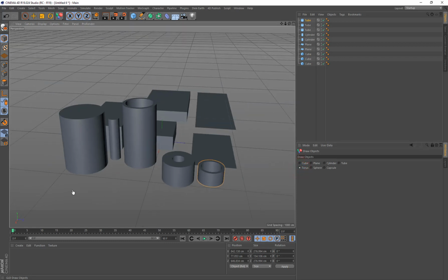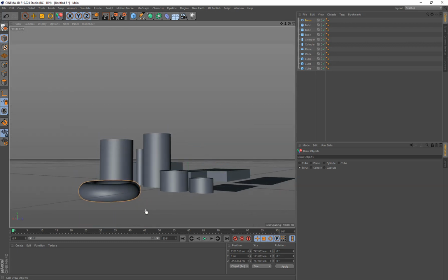Torus, a little bit interesting as well. You drag to define the outer radius, you let go, you may not see anything, because now you're defining the radius of the torus itself. And you're doing that by dragging up in the height direction. So if I come down to the lower level here, if I can drag it out, drag it up, you see you're kind of on the height of the torus.